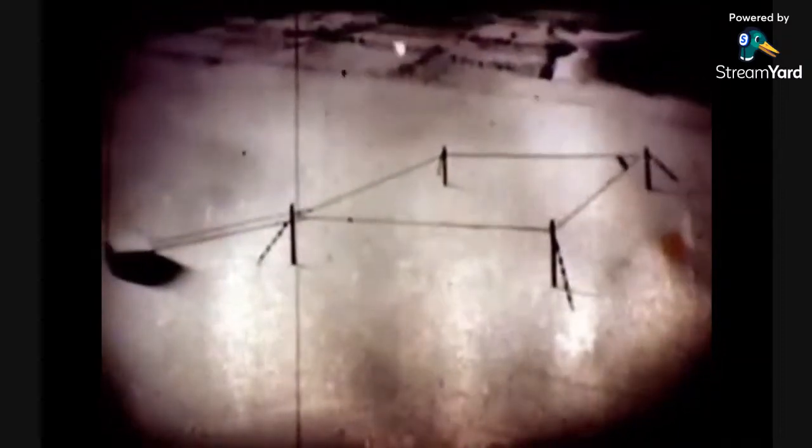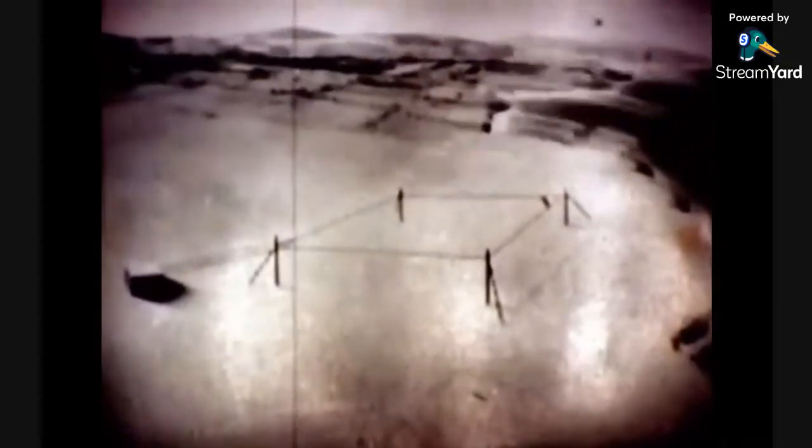Here the resistor does the same job as in the single long wire. The combined energy from both V antennas radiates in the direction of the resistor. Such a design, therefore, produces a much more directional pattern. Yes, it's truly pinpoint pattern projection across the ocean. But this ground antenna system, like the others you've seen, may be used for communication with aircraft. So let's analyze aircraft antenna systems.